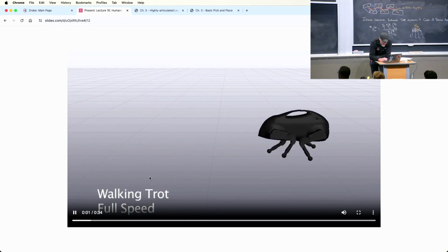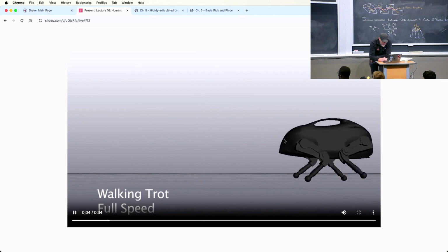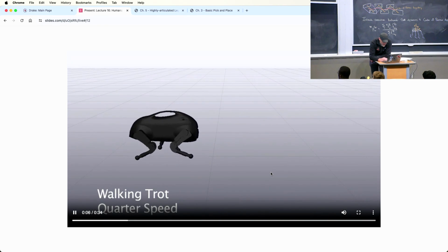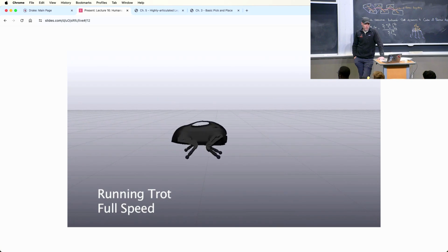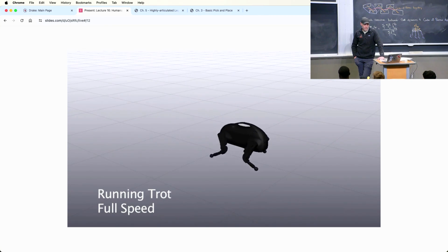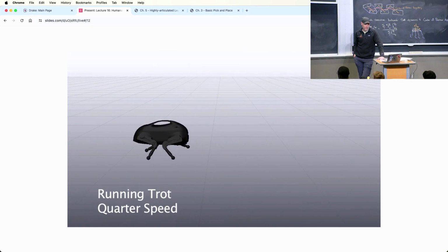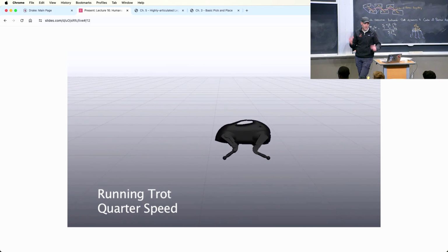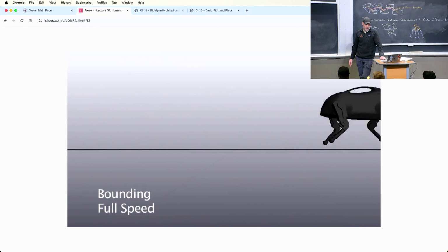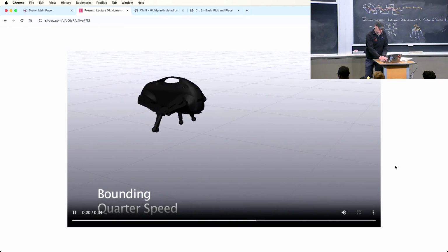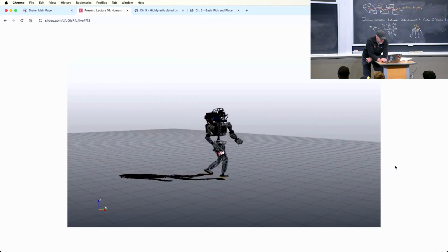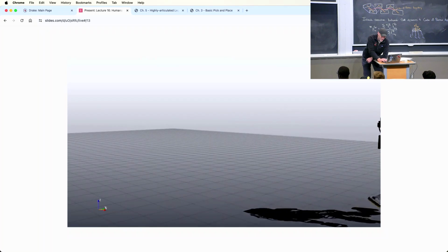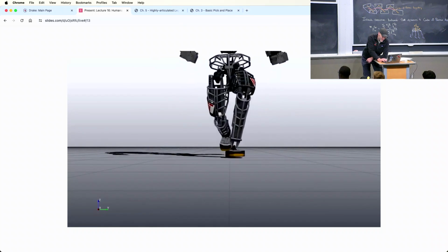And that is exactly, actually, when I showed, I simplified a little bit when I presented the first time. I said it was just hybrid trajectory optimization. But it wasn't actually in the notebook. If you look at the notebook, it's not actually using the full dynamics of Little Dog. It's writing the centroidal dynamics plus constraints on the forces to do the planning I showed you before. And we made Atlas run this way, although only in simulation. We were too afraid to break the robot before the competition.